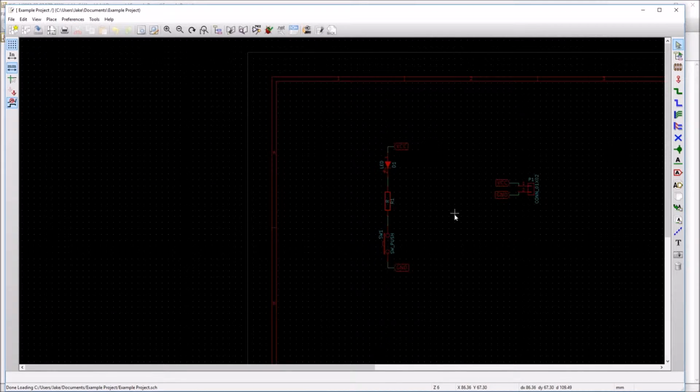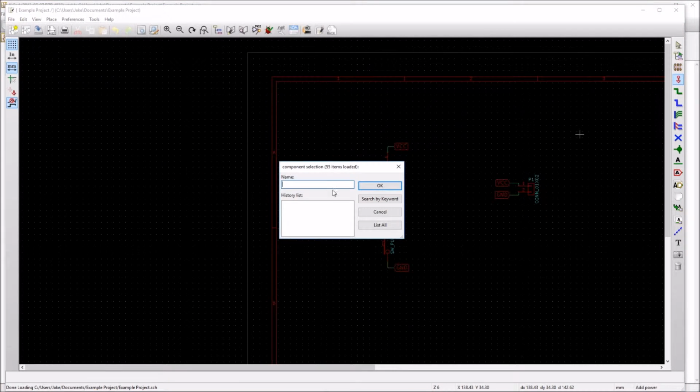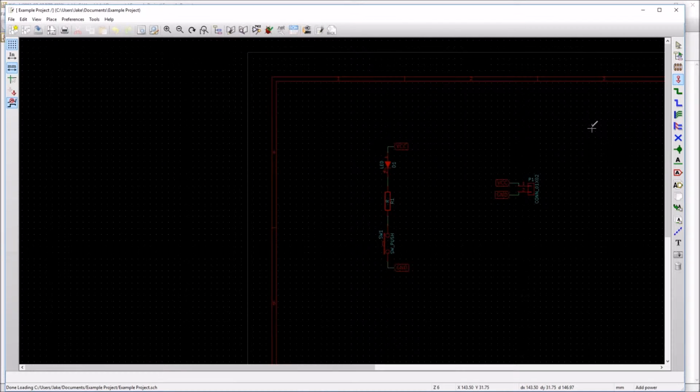So to start off with, we're gonna have a look at the PCB or the schematic editor. This is very similar to Eagle. It has a couple more features. I don't believe Eagle has this, which is basically you can add in positive, negative, and ground. So plus 5 volts, minus 5. There's a whole bunch of them. It has pretty much all your normal traces, your buses. This one has global labels, which I don't know if Eagle has. I definitely didn't use it when I was using Eagle.